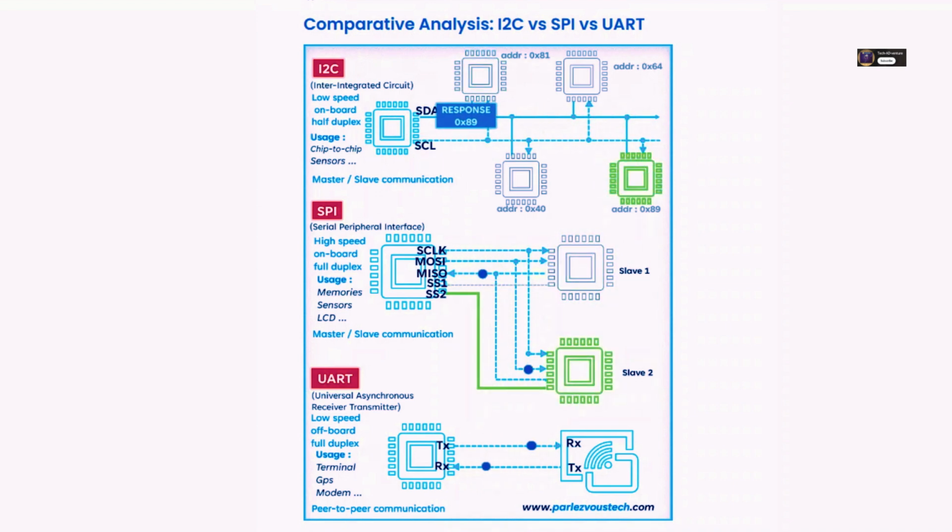And what about UART? I know that's often used for basic serial comms connected to a PC for debugging, maybe? Right, UART, Universal Asynchronous Receiver Transmitter, also uses 2 wires, transmit TX and receive RX. And this is key, UART is strictly point-to-point, meaning it's designed for communication between just one sender and one receiver. You can't just hang multiple devices on a UART bus like you can with I²C. If you needed to talk to 10 devices with UART, you'd literally need 10 separate UART interfaces, each with its own TX and RX. That eats up microcontroller resources like crazy.